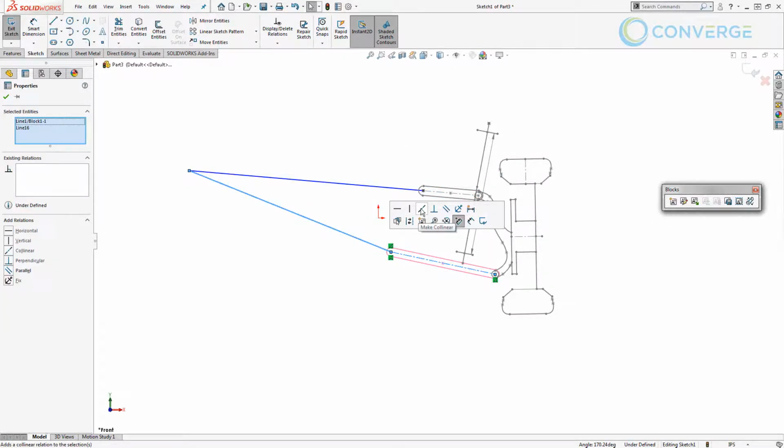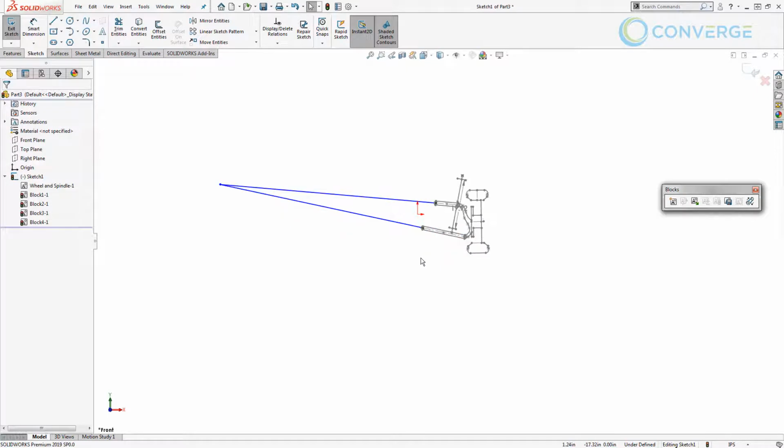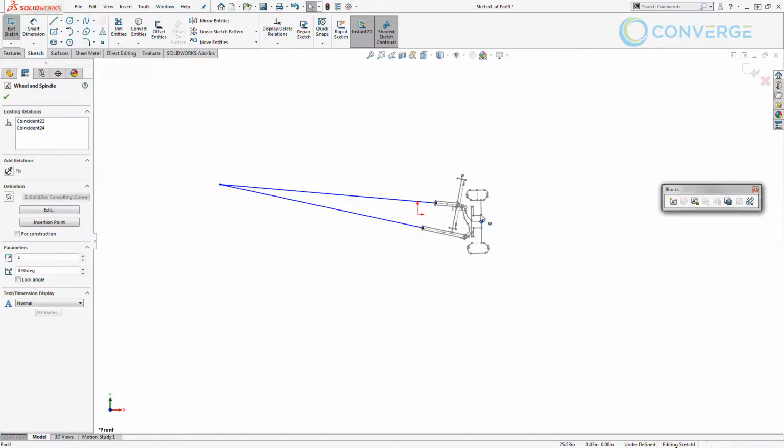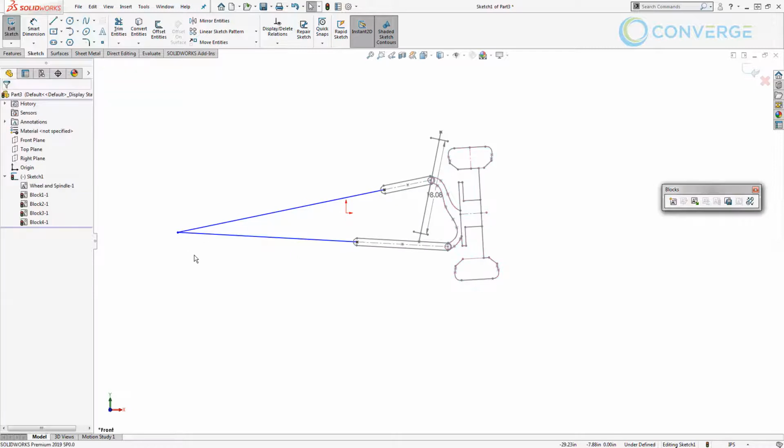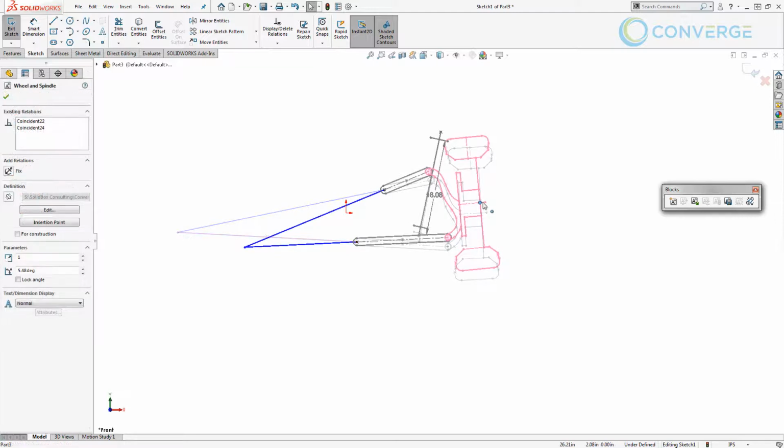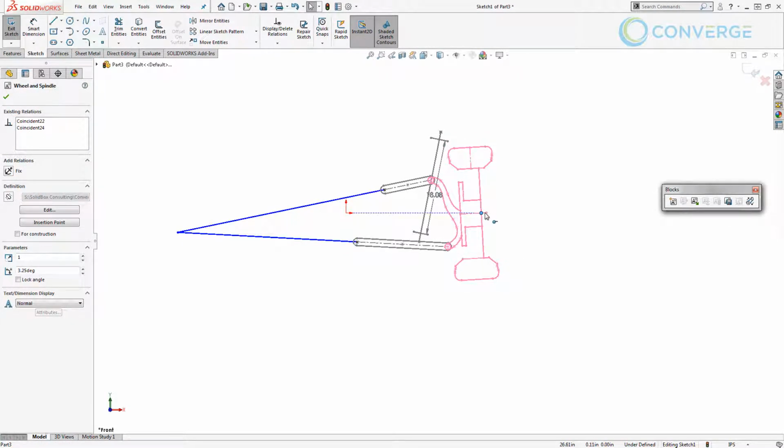All right, so this is an important factor when we're talking about suspension, understanding where we have that virtual point that these two links connect to. It's a key point in understanding how the vehicle handles changes in suspension travel and what that's going to do to the overall vehicle. So having this point, we can then get a dimension from it. We can understand where that point's going, what the angle is in relation to the ground, and how that affects the overall suspension.